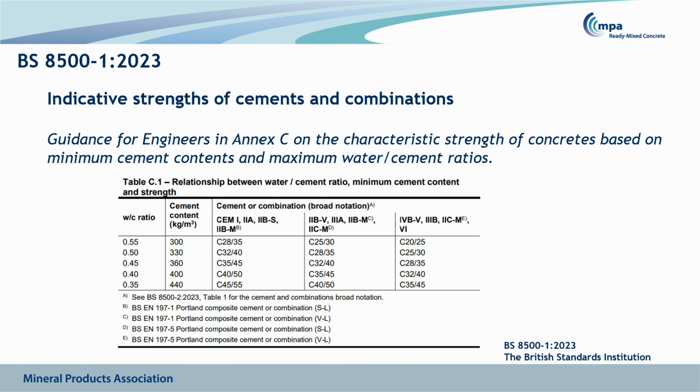A control of compressive strength was also then added. So that gave you an indication that the quality of the materials was about right. So we had 28-day strengths and we had slump tests on site, and you could probably gauge that the concrete was correct. And this really was at a time when plants were manually batched. We didn't have autographic records to be able to look and see what was produced. All records were manual.